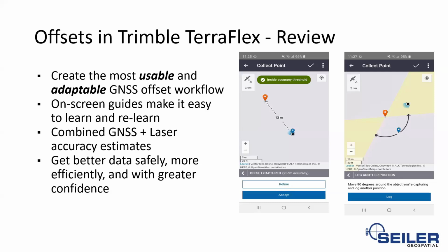If, again, that shot is not what you intended it to be, or you think there might be something wrong with maybe your GNSS signal, or maybe your VRS real-time correction, or you did forget to calibrate the laser, then you could start over, or move on to the refined technique and then move 90 degrees and get yourself your second shot.